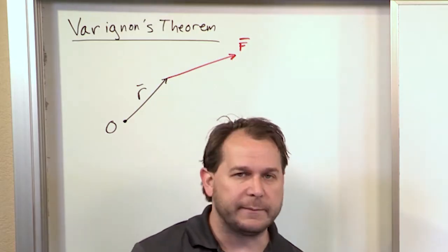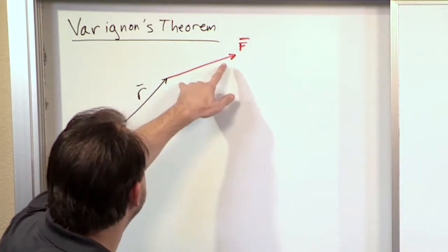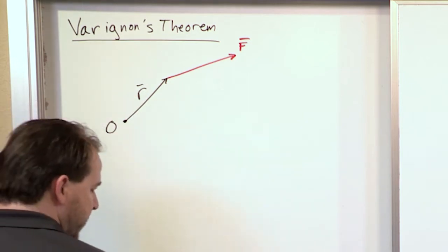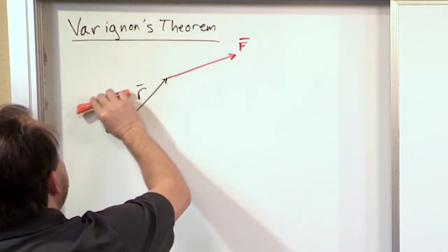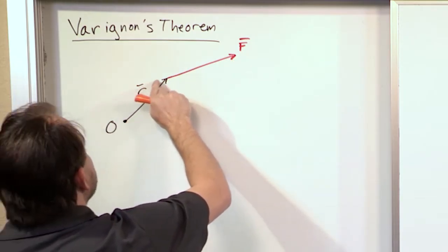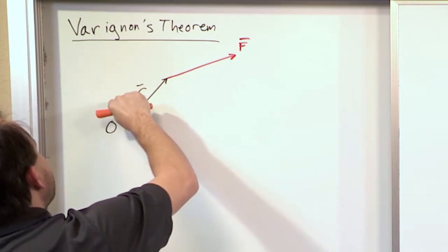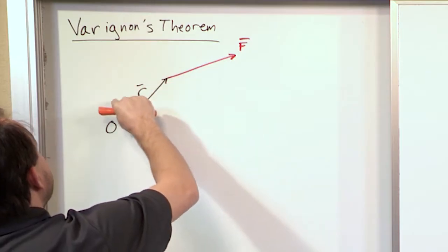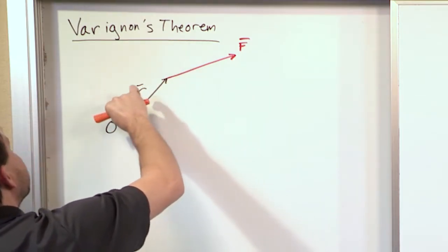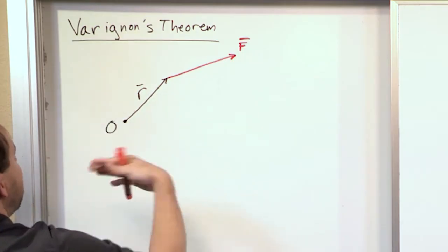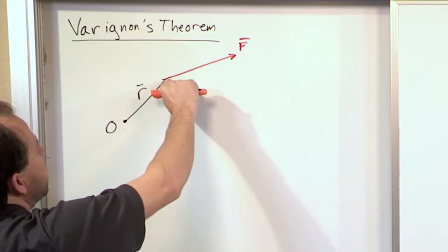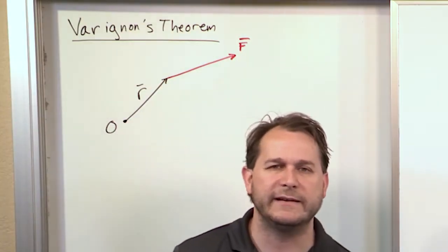Alternatively, we've talked about the fact that you could use the full-blown force and find the perpendicular distance to the line of action. This force's line of action is going like this. So if I draw a dotted line this way, here is the line of action. The perpendicular moment arm to the line of action would be this distance from here to here. So I could use the full-blown force multiplied by the perpendicular distance, that'll give me the moment, or I can use the full-blown distance and just find the perpendicular force. We've gone through this many, many times.